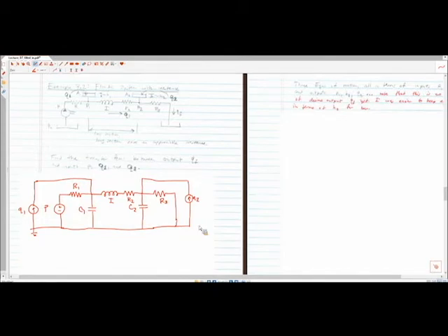Any questions about the electrical circuit analogy? Yes? How do we get the capacitors? So these are tanks, and therefore they store pressure, right? If we look at this like a swimming pool analogy, the bottom of your swimming pool has the highest pressure. This is a tank. We're filling up the height of the tank, and that's creating a pressure at the bottom. Just like the accumulator, where you're storing an elevated pressure, here we're storing an elevated pressure as well. If it rains, the pressure will get higher. So it's still a capacitor, still storing the pressure in the system. But now the rain is indicated by this fourth leg of this node here, which is dumping in, in this case, flow rate.